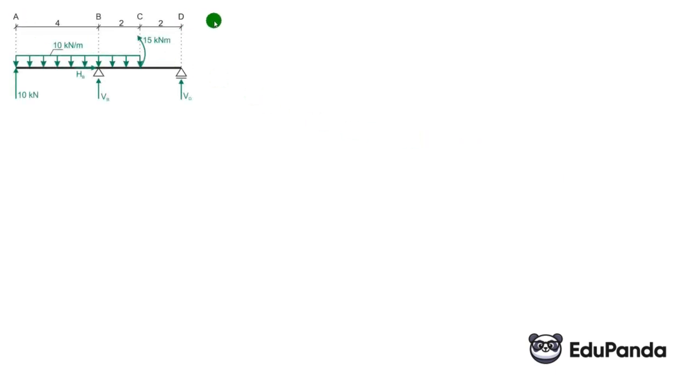We know that in a non-sliding hinge support, we have two reactions, horizontal and vertical, while in a sliding hinge support, we have one reaction. So at the beginning, we obviously calculate the reactions at the supports. First, we can do the sum of projections on the x-axis. We only have one horizontal force, HB, which is the reaction at the support, so it must be equal to 0. Next, we'll do the sum of moments, and we could do that either at point B or at point D. It doesn't matter, I'll do it at point D.